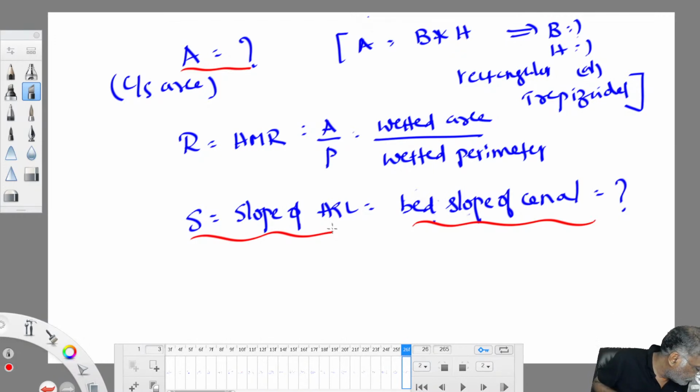Civil engineers, canals are very, very important. They are part and parcel of our life. Anyway, generally we prefer pressure conveyance to gravity conveyance, because gravity conveyance is initially more economical, but over a period of time, pressure conveyance is more economical, especially in tropical climate zones where evaporation losses are very high. In open channels water evaporates.